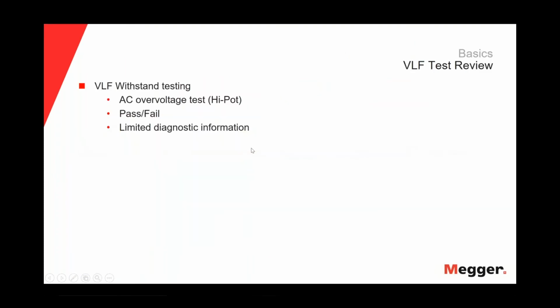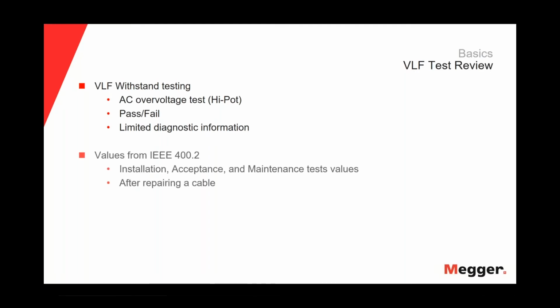So, doing a quick review of the VLF test, we can say that the VLF is an AC overvoltage test. It's a go or no go test. That means that the cable will pass or will fail during the test, and the VLF test will provide limited diagnostic information.